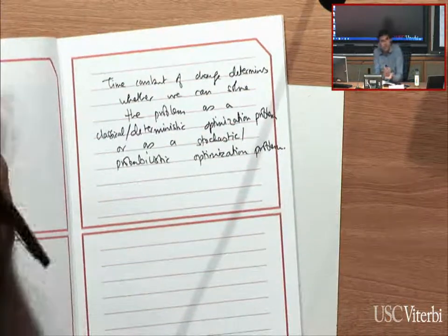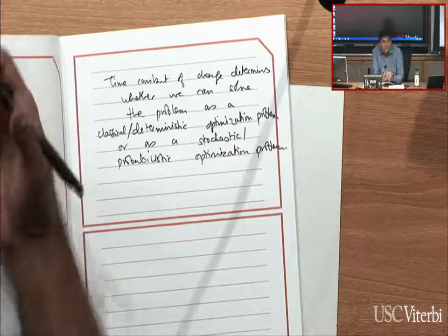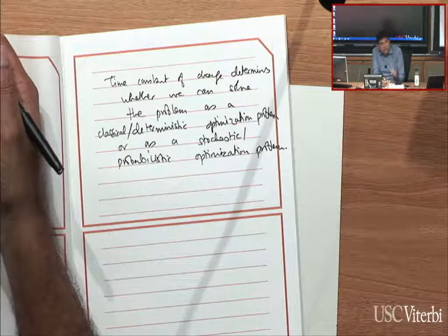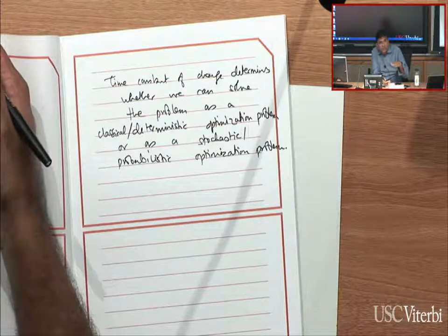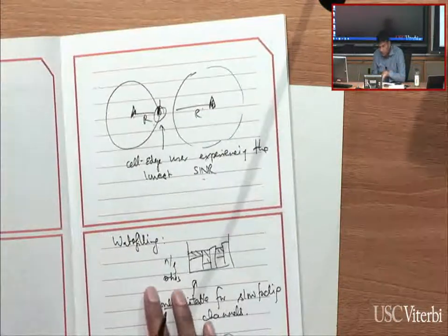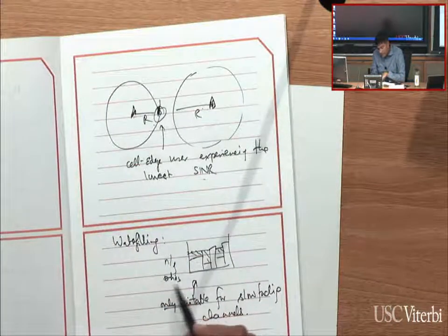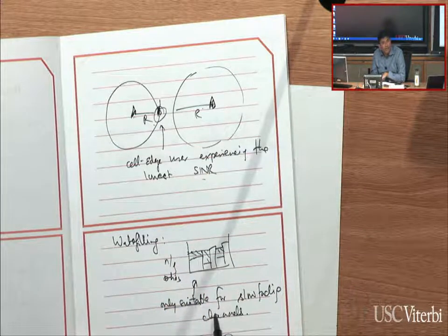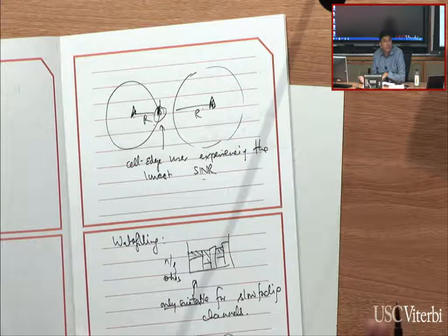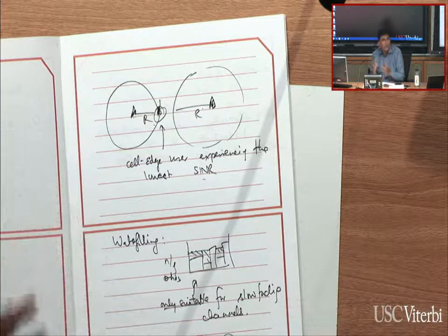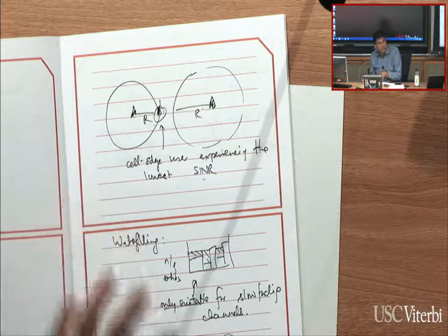And particularly when we get to wireless networks, the environment changes will be a function of what environment you're in. Some environments actually, this link quality does change very slowly, as we talked about. In other environments, it does change very fast. So if I apply stochastic water filling by estimating the gain to noise ratios in a slow fading environment, that's fine. But if I have a fast fading environment, doing this means that whatever gain to noise ratios I'm using are probably incorrect for the instance, or by the time I learn them, by the time I apply them, things might have changed. Right? So this time constant is really fundamental to whether we need to worry about probabilistic modeling or not.